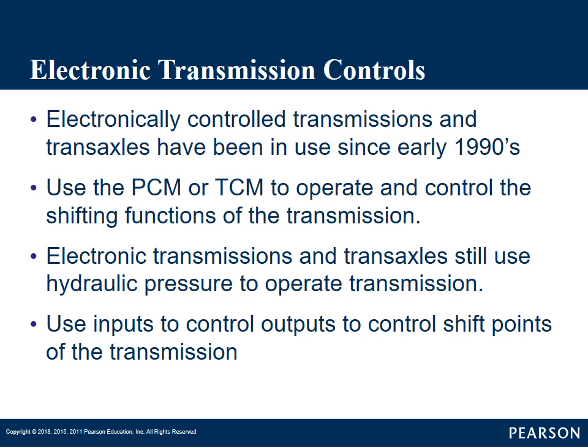The other thing about transmission control modules: many of our PCMs and TCMs are mounted under the hood, separate, in aluminum cases, usually finned to help cool them. We're starting to see more and more transmission control modules mounted inside the transmission on the valve body with the solenoids. So if you needed to replace solenoids on some of these, you replace the whole assembly, module and solenoids all together.